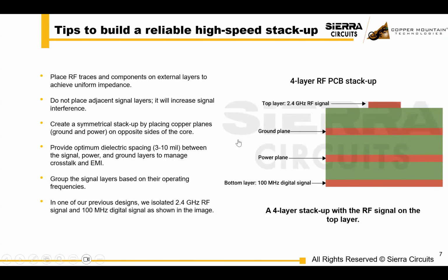we manufacture with cores and prepregs, so a core does not change its dielectric height after lamination. So a lot of customers put cores on the outer layer. So layer 1, 2 would be a core. And this ensures a consistent dielectric thickness throughout the length of the board and the length of the sheet that we use to manufacture. Also you can be very conscientious about component placement and how you separate the sensitive high-speed signals, RF signals from, let's say, power components.